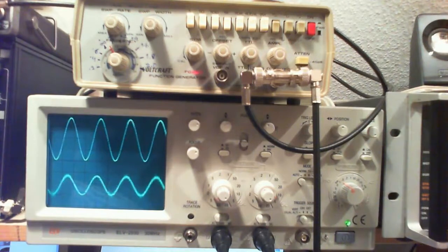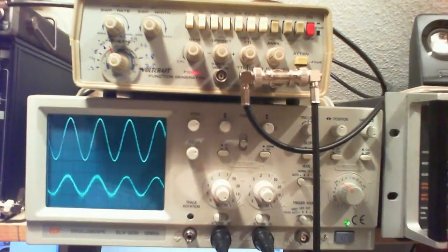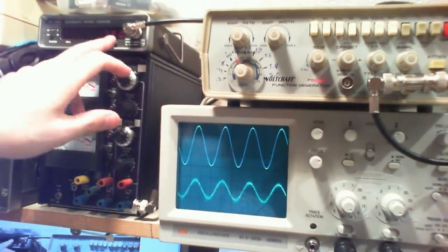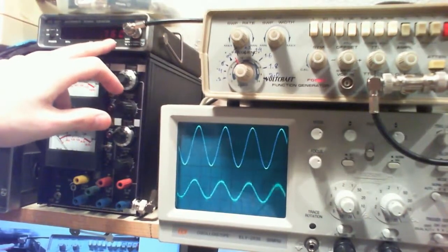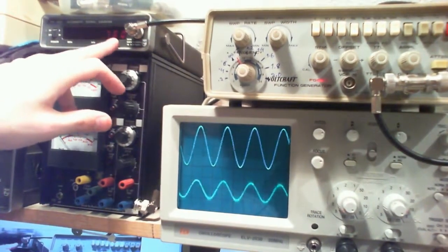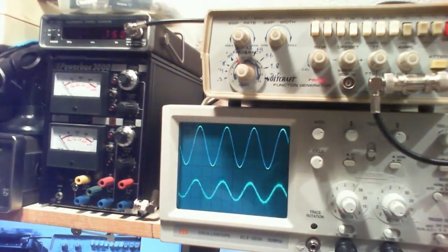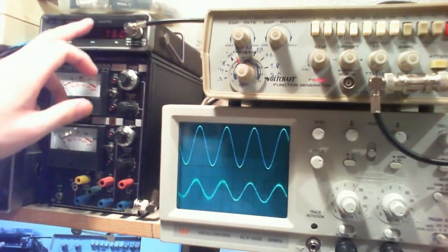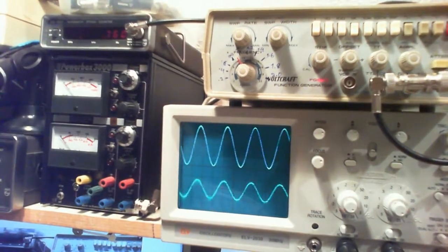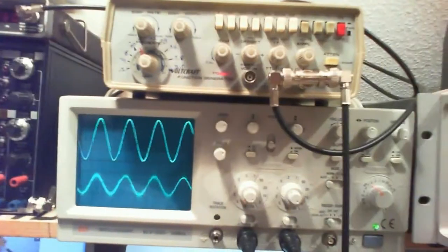And if I take the reciprocal of that, my frequency is 770 hertz. 770 hertz, and you see that the counter is giving me 760 hertz. So that's why I say that I don't trust this counter at low frequencies. I guess above 2-3 kilohertz or so it's going to be fine.